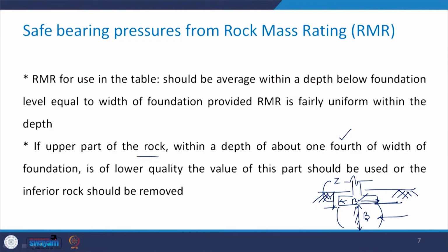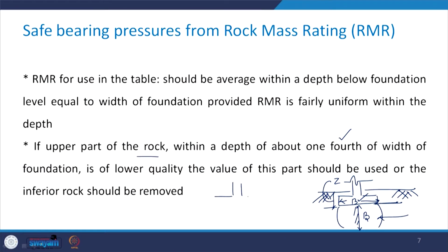Now, in case the upper part of the rock, within a depth of about 1/4 of the width of the foundation, is of lower quality, then the value of this part should be used, or the inferior rock should be removed. Let us try to understand with the help of a figure again.